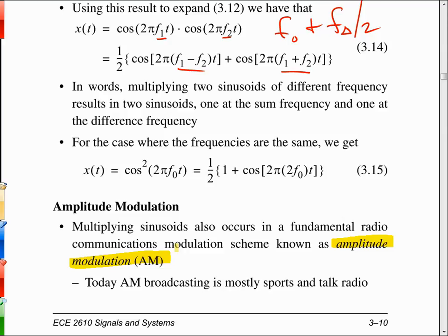But it does have a nice characteristic in that AM radio signals are at a much lower frequency than the FM broadcast frequencies are. So when the ionosphere shifts at night, we can get skip off the ionosphere, which means a radio station in New York City can be picked up here in Colorado Springs. FM radio is a much shorter wavelength, and it just penetrates through the ionosphere. It does not bounce off of it.